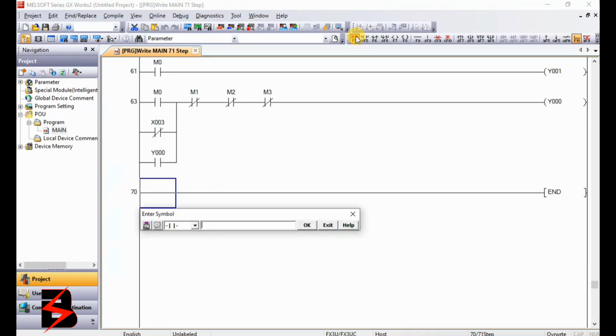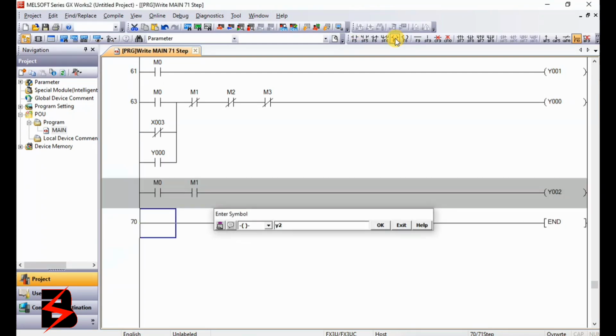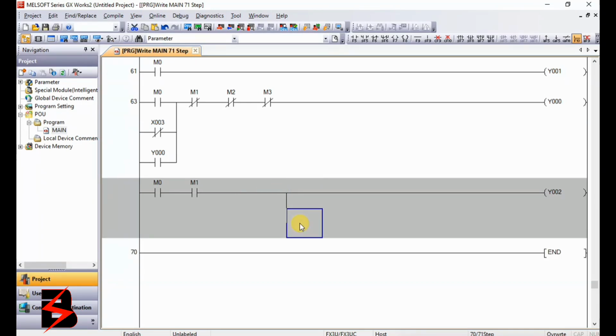Once our system is on, that is M0, M1 is going to turn. That is M1 is going to power on the blue sorter, which is the coil here, and it is Y2. I'm going to have a branch here. It is going to turn on sorter turn, blue turn with the blue belt. Also for green turn, green belt. For gray turn and gray belt at the same time. So here, this one is Y3. And this one is going to self-hold.